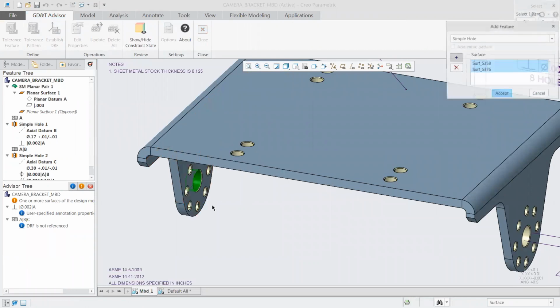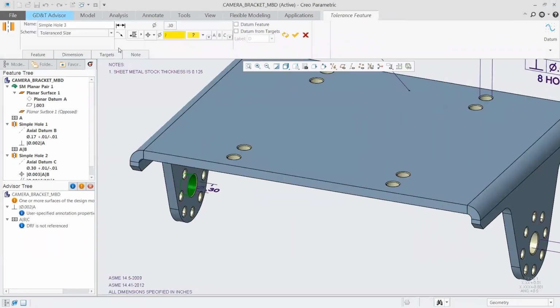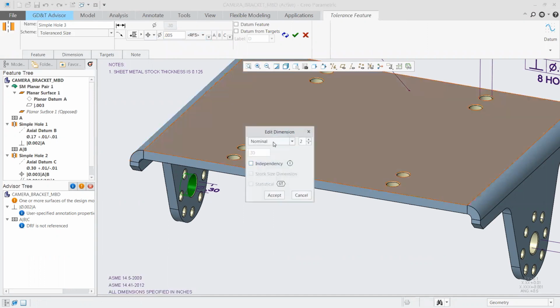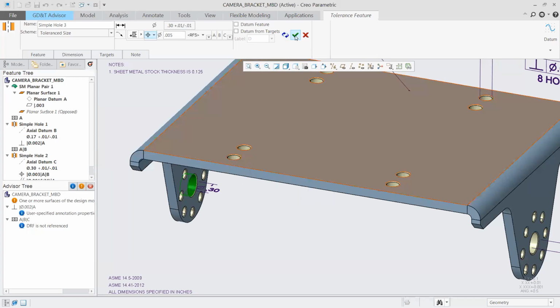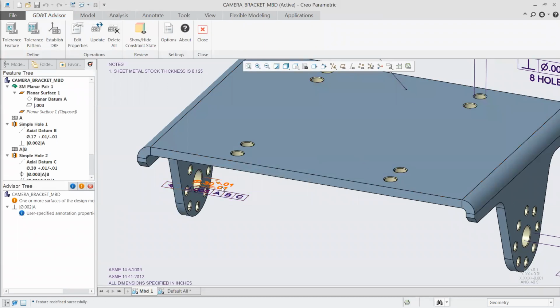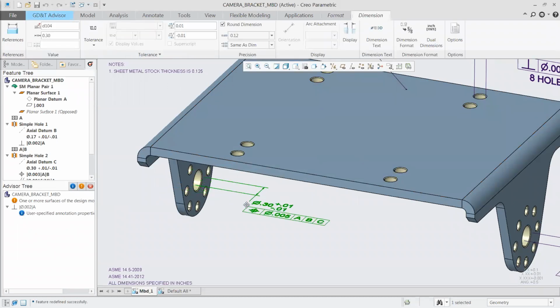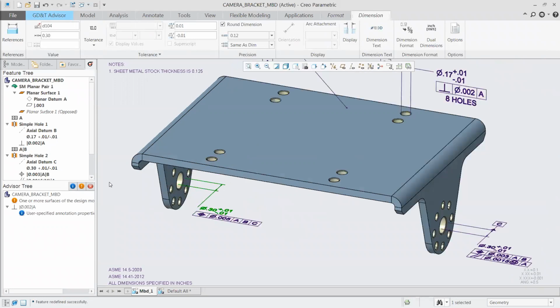And building out another one here on the left-hand side, we can start to define the hole down there at the bottom. So for that one, we're just going to need a positional tolerance here. Okay, we can give it a value, give it a reference, again, a specified range. And because we don't need a new datum there, we just accept it as is, and we can just drag that box out so it's able to be clearly seen.